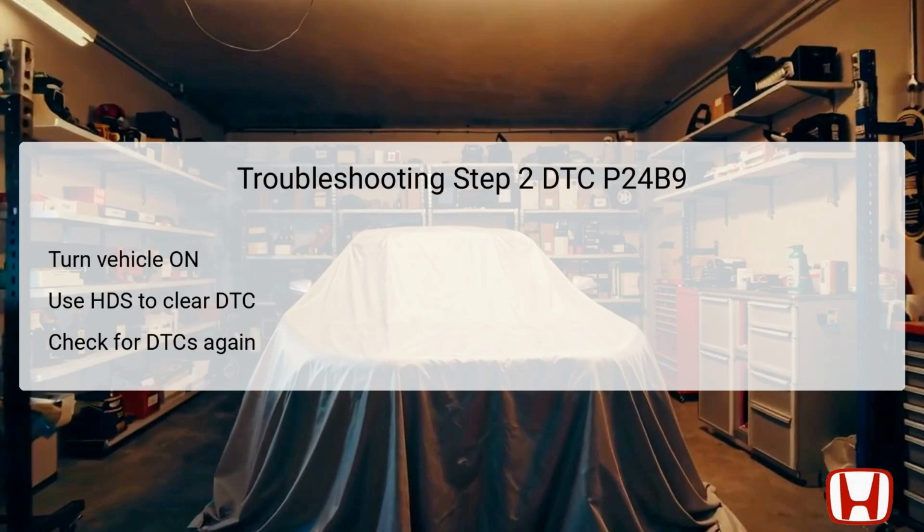In the second step of troubleshooting, the technician must turn the vehicle ignition to the on position without starting the engine. This action powers the vehicle's electronic systems, enabling the use of the Honda Diagnostics System, HDS, to clear any stored DTCs. After clearing the DTC P24B9, the technician should turn the vehicle off, then back on to refresh the system and ensure it is accurately reading the data.